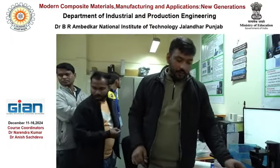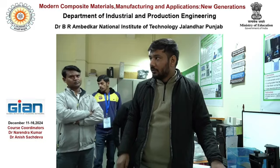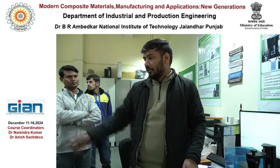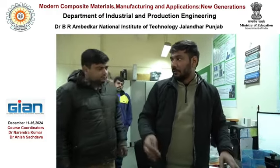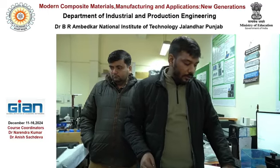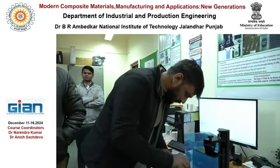we have to fill the tub with the required material we want to print. Right now this is the flexible epoxy material that we have shown there. So this is the material we have filled. We have to fill it at a certain level so that if a large part is there, shortage of material won't be there. So we have to fill at a certain level. After filling the vat with the required material, I think the software gives the amount of material required for the printing.